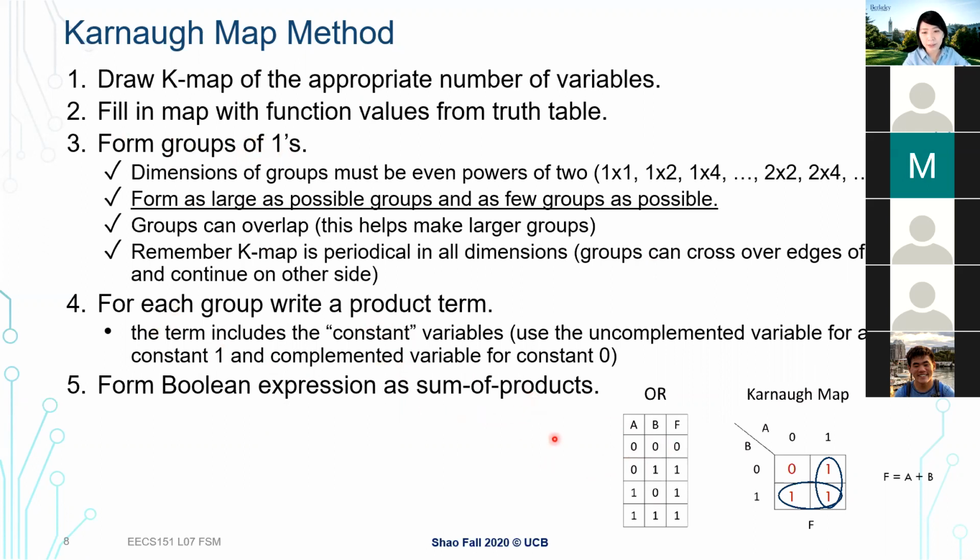And then by summing all the product terms together, we can actually get a simplified function. So this is a very simple truth table. If we want to turn this truth table into a Karnaugh map, we split the two inputs into different dimensions, and fill the Karnaugh map with the expected output. Turn the last column of the truth table into the Karnaugh map, and then I start drawing circles. Whenever I have a circle here, it means at least one of the inputs can be eliminated.